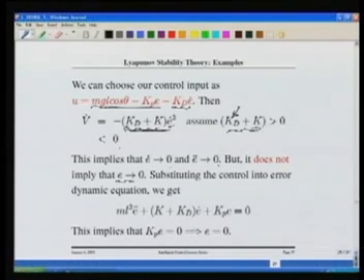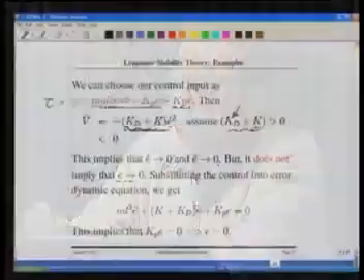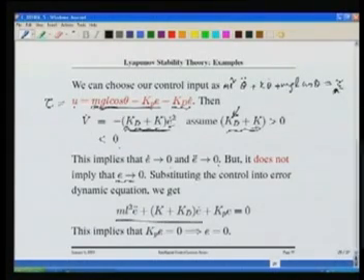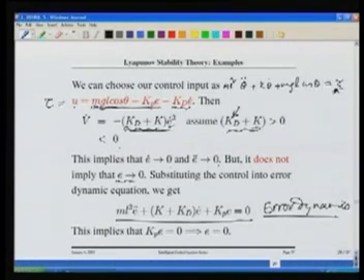So, we take this control input and replace it in our system. Normally the control input is denoted by u, but actually this is tau, and our actual system is theta double dot ml square plus k theta dot plus mgl cos theta equal to tau. So, this tau is here and I bring this quantity and put it here. If you put it there, you get this equation, and this is the complete error dynamics, the actual error dynamics given the control law.